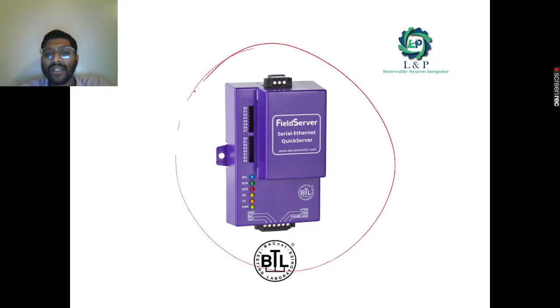This is the FieldServer serial Ethernet quick server. As you can see here, we have two ports. This is going to be R1 and this is going to be R2. As system integrators, we recommend you use the R2 port because you have indications here. You can check whether you have proper communication with the TX/RX indications. If there is no receiving, you can identify it with the indication itself. So it's an easy way to cross verify whether your communication is good or not.